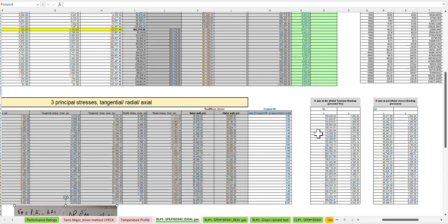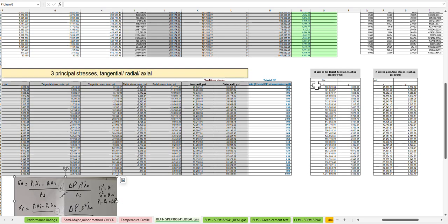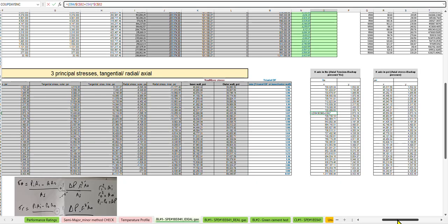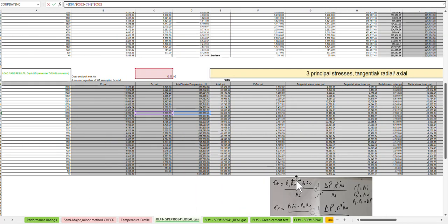As a result, for the load case, this is the value that you are going to plot on your design limit plot. One important thing here: this one is self-explanatory, it's the differential pressure from the internal to the external. However, this one has the backup included. Here you can see the backup for the burst load case is the external pressure.